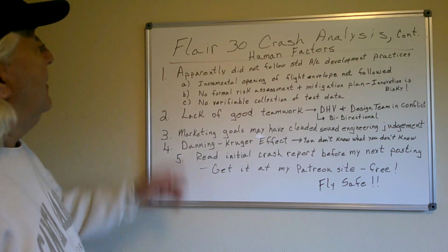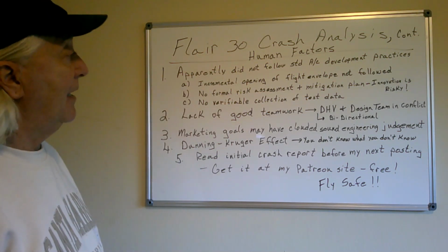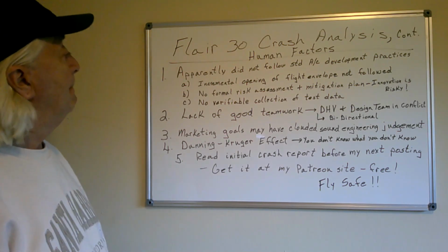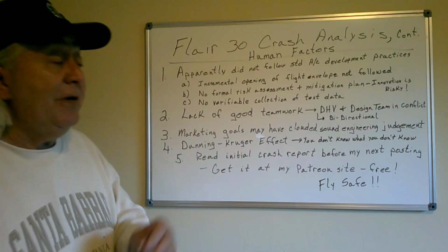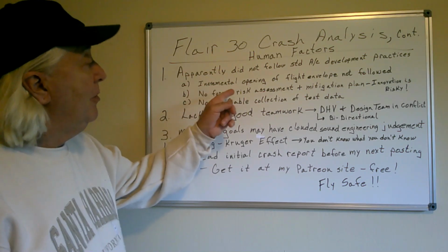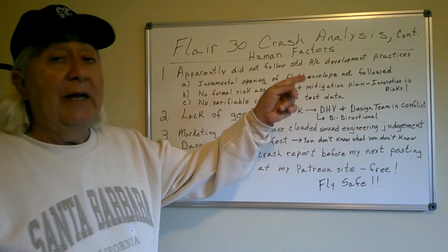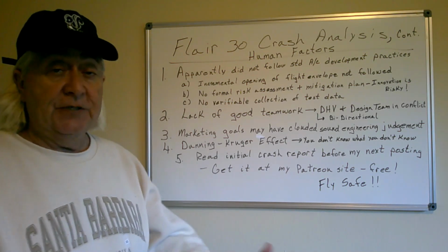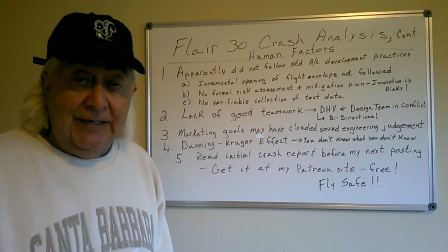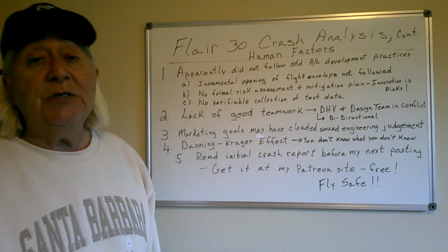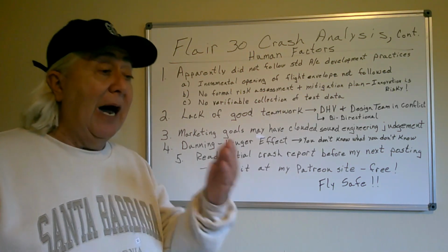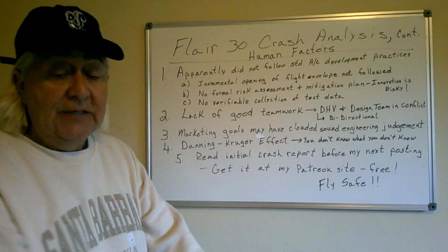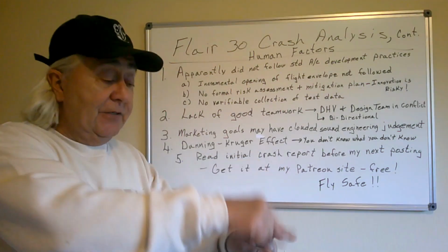Okay, so apparently they did not follow standard aircraft development practices, which you've heard me already allude to. And the main thing we do, I talked about flight envelopes. We do an incremental opening of the flight envelope, and that was probably not followed. How do I know that? Have I seen data, written reports, stuff like that? No, I haven't. But as an engineer who's done this for decades, I see what's missing, or some odd fact. And I go, oh, the only way that you could get there is if you went here, here, and here. And that's the only way to get there.